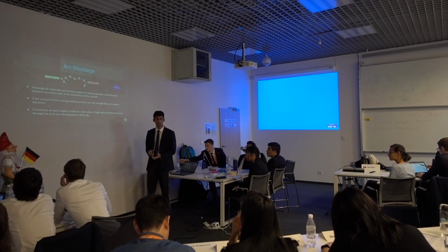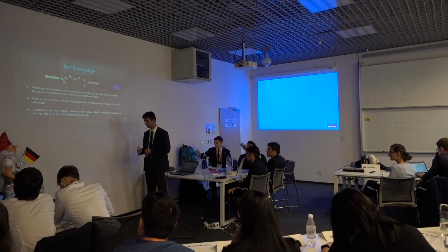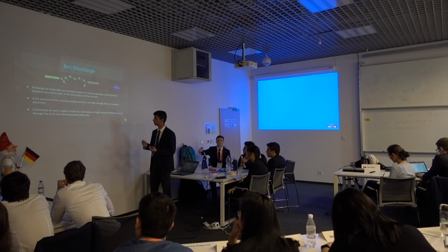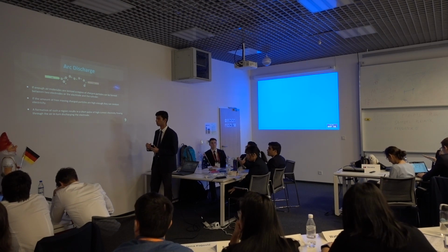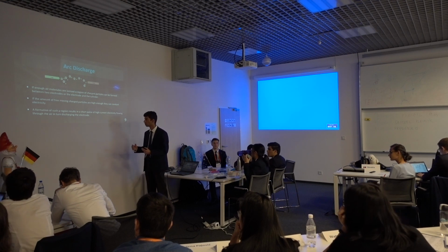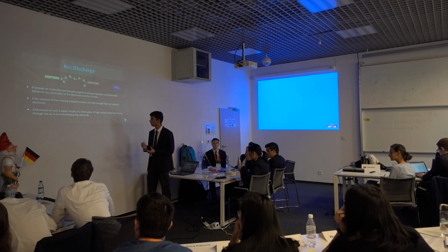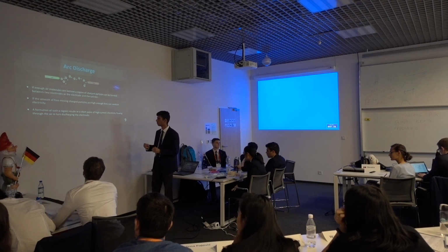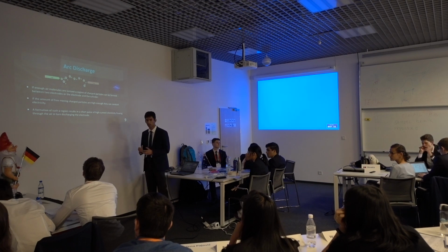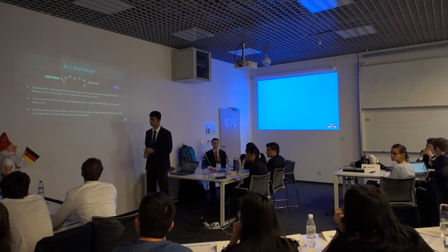So, arc discharge was seen in our experiments, and I would like to give an explanation beforehand. If enough air molecules are ionized in a region between two charged electrodes, there is a region of free moving electrons, and if there are a lot of them, they can create a sort of plasma which current is able to flow through, and that means that the electrode will discharge and a spark will be created.